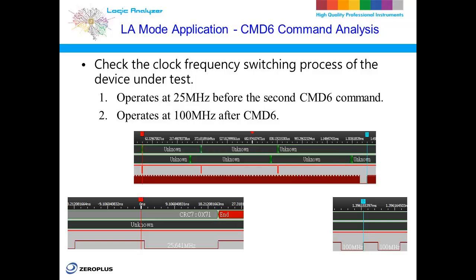and shape changes. We will examine waveform stability and verify clock signal integrity. If the waveform shows abnormalities like jitter or instability after the transition, it could indicate an error in the mode switching process, requiring further configuration checks or adjustments. To ensure the clock transition post CMD6 is correct, we need to perform the following checks in B2.